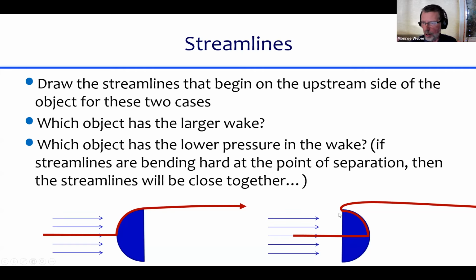See that? This part right here is what's critical. There was fluid that was coming out of the hemisphere that had to turn around and reverse direction. And you can't just do an instant change in direction. The F equals ma law makes that illegal. So you have to turn around slowly. And so that's what makes this extra little bend out here, and means that the streamline ends up being away from the body where it's separated.